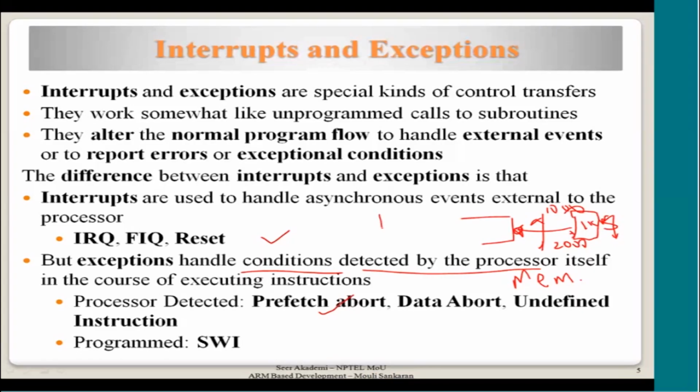Or it could be a ROM sitting in the chip, on your board. The ARM core is trying to write into ROM memory. You know that with read-only memory, you can only read from it, but you can't write into it. By chance, some error has happened and an illegal pointer is trying to write into ROM. Then the memory system will respond back saying that there is a data abort: you are trying to write into me, and I am only a read-only memory.